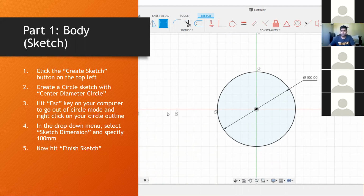So first thing we're going to do is specify a plane. We're going to choose the XY plane. All right, and now that we're here, you can use your mouse to scroll around and grab parts and things like that. So we're going to first create a circle using the circle tool. So start out at the center and drag this out. We really don't care about the length, so I'm just going to do a random length here.